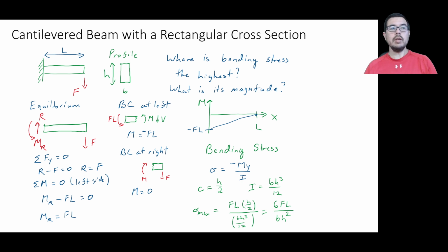So the thicker I make it, the lower this stress can become. It's going to be proportional to the width of the beam, not squared, just b. And it's going to go down as the length increases. It goes with 1 over L. The strength will go up with thickness. And so you can see there's the L, there's the b, there's the h squared.